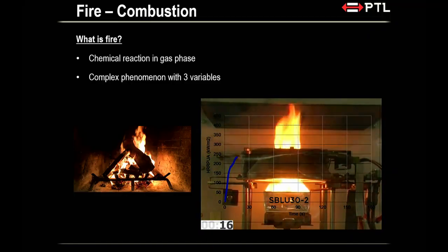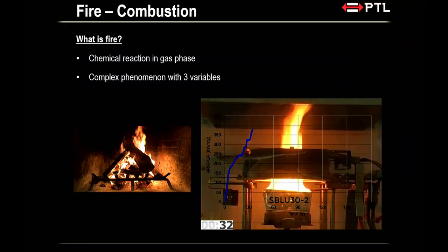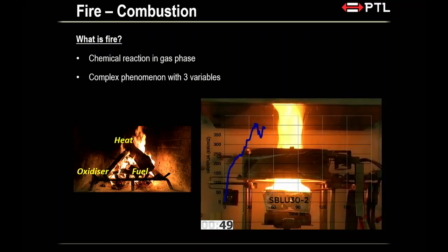So this is actually how we quantify or define a fire. So heat release rate, the unit is kilowatt per meter square of fuel surface area. The horizontal axis over here is time. So what's happening here is, okay, your solid ignited, it's going through its growth phase, and eventually you will see it reaches its peak heat release rate, it will plateau, and when the fuel is consumed, it will decay. So flame is a chemical reaction.